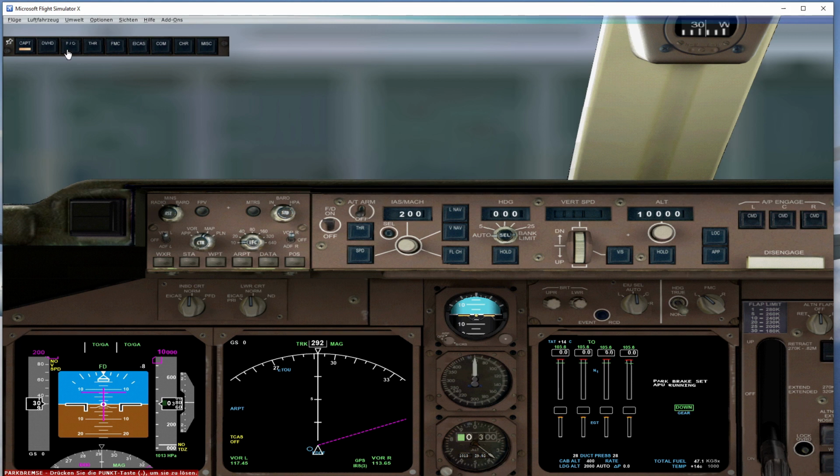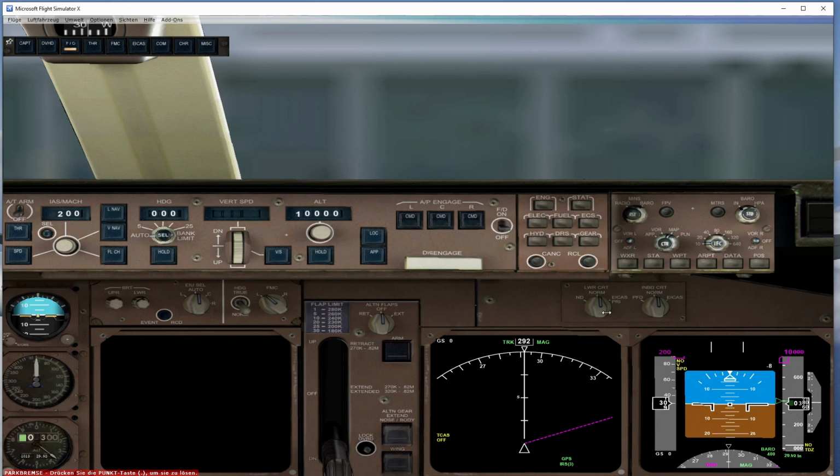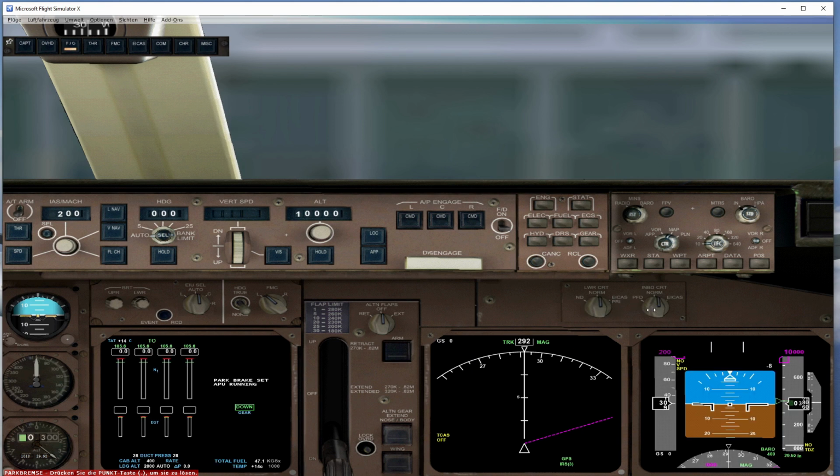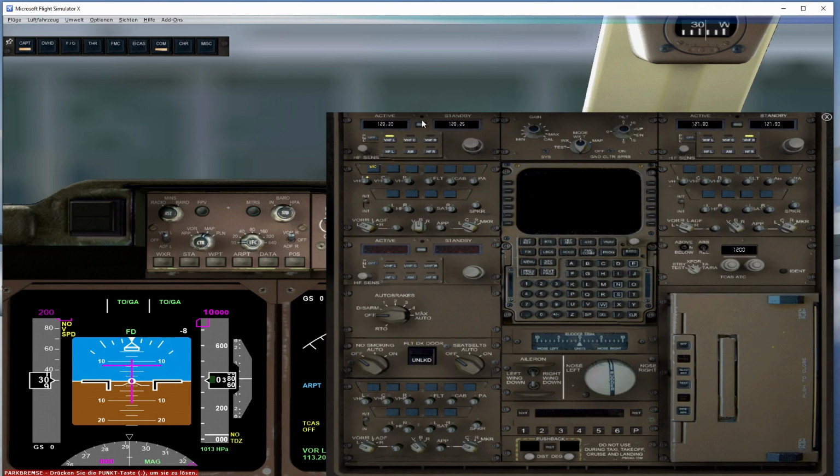Now, we can go to the first officer side to see the gear indicator better. But they should just be closed and they should be off. And same here, we can switch around the displays. And as well, this flight director switches on as well, but we stick to the captain side first. Then we go to the center pedestal, where you see the frequency here, active VHF left,